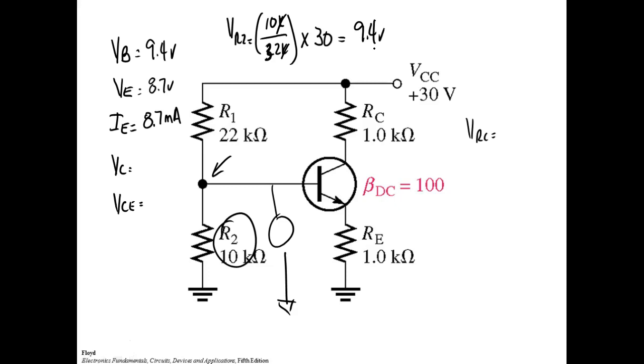What you do when you take Rx over RT is that gives you the ratio that resistor drops in that circuit. And what's nice about using the voltage divider formula is if I was to come up here and make that 40 volts, the ratio would still be the same, right? You understand that? So what you learned in DC, they should have taught. Did they teach all the voltage divider formula in DC? They should have.